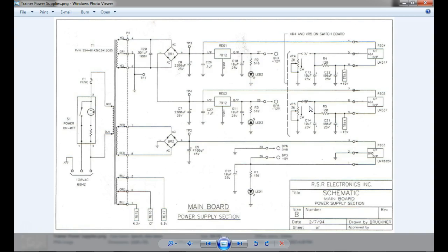So this is our plus 5 volt regulator right here. It's a 7805, but it's an H series, like a 5 amp regulator. This is the little LED that comes on. Here's our filter capacitor, 4,700 microfarads, 16 working volts. Y'all understand that now, right? There's a 7912, so what's the 7912? Negative 12 volt regulator. And over here, this is the terminal that sits up. It's labeled negative 12, right?